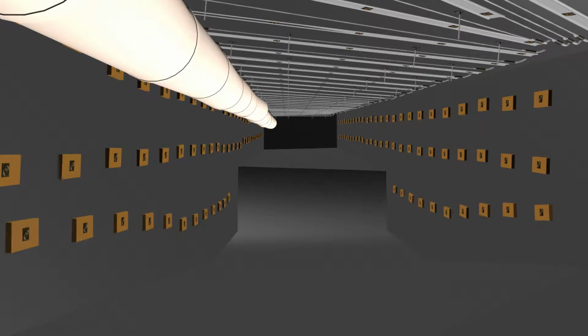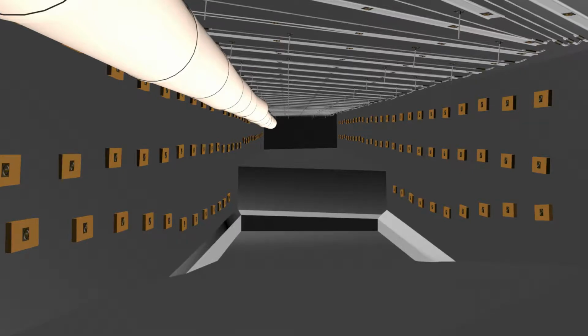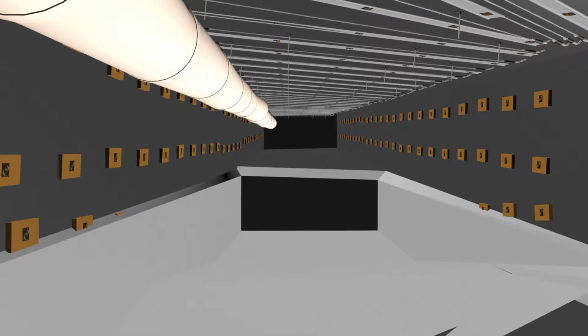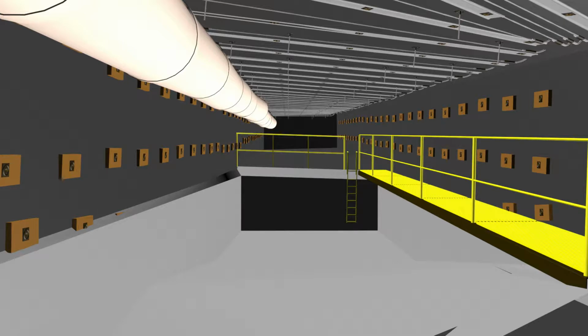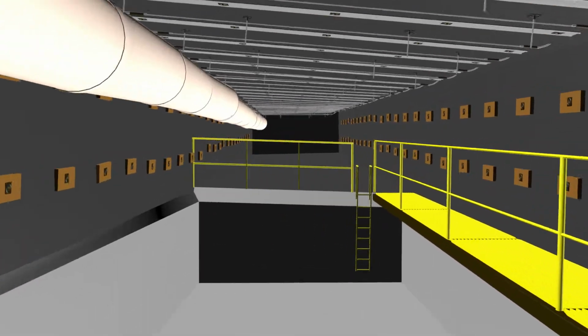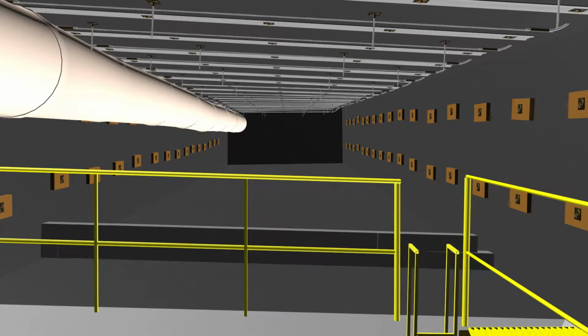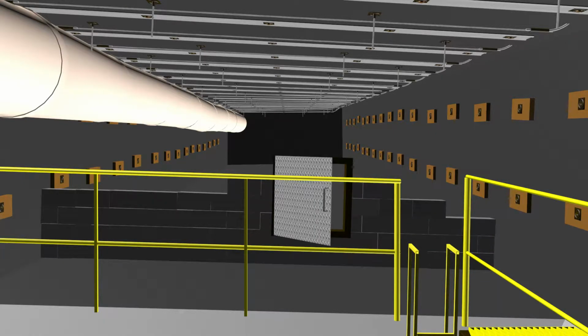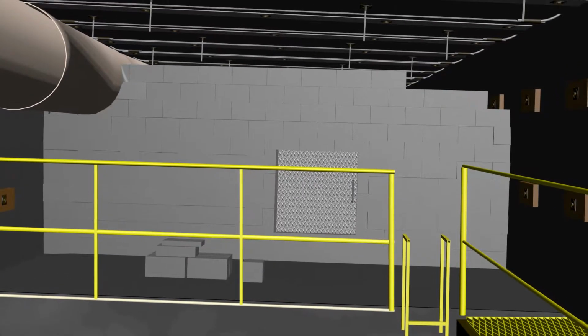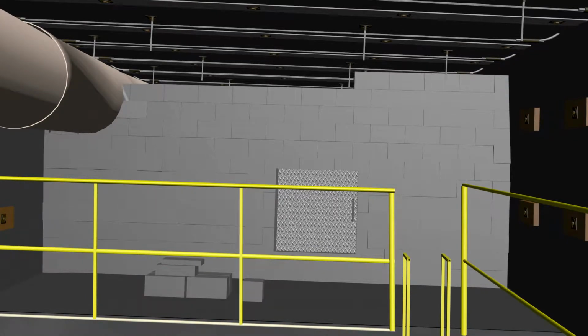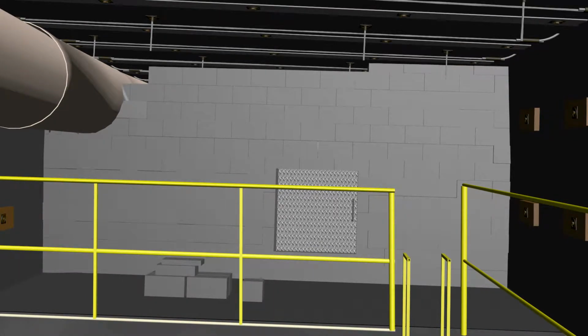Once this area is excavated, it will then be lined with concrete. A walkway, a ladder, and handrail are installed to allow for examinations. A block stopping is then constructed in by the sump. The vent tube will remain in place through the stopping until the advancement is completed to the air shafts.